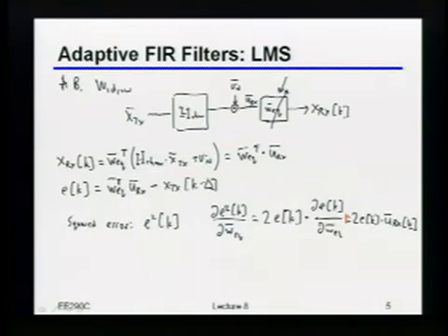In an amplifier, when you want the error to be 0, what do you do? Negative feedback. Yeah, you put it in negative feedback with infinite gain at DC, which means you integrate it, right? So, for those of you who like math, this is just another way of saying that you build a loop where you just follow the gradient in terms of what should be the value of the coefficient.